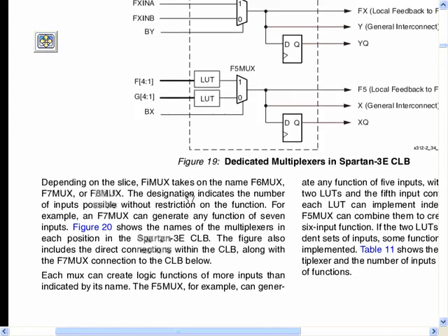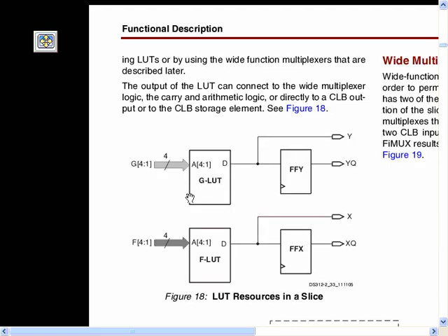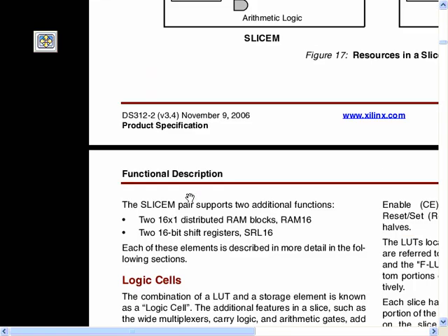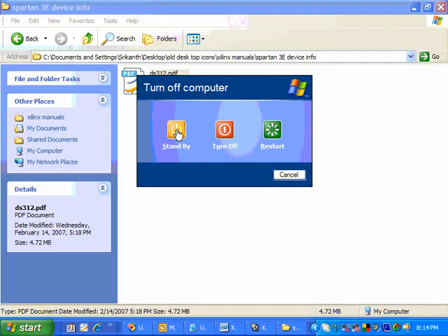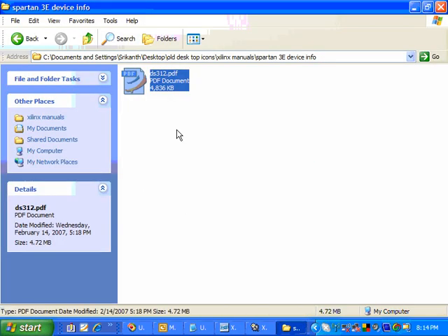He talks about, you see, Spartan 3 FPGA having dedicated multipliers, their connections, a lot of things. Generally, when you are trying to develop an embedded system very seriously to optimize its performance, we try to understand the architecture of the FPGA, and within our area constraints, I will appropriately make use of the resources in the FPGA. For example, I need a multiplier. I will map the multiplier into the hard multiplier which is there in the FPGA. So I get a high speed like that. So I am coming again on Monday.